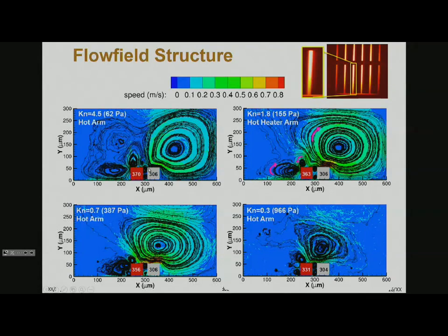This was a complex case because of all these vortices forming. We actually had to go with a lot more particles per cell. At some points, when I say 20 particles per cell, you start that off and see how it works. In this case, though, we were seeing that some of our sampling on the vortices didn't look so good. So we ended up increasing, I believe, to 100 particles per cell, and that's when we started getting the resolution that we wanted.